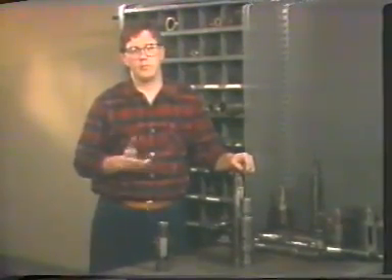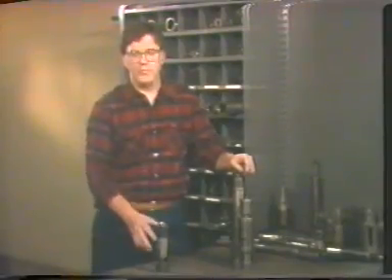Pulling tools are designed primarily to be used to retrieve subsurface devices from the tubing bore. Such devices are designed and constructed to provide a place near the upper end of the device for a pulling tool to engage or latch the device so it can be unlocked and retrieved from the tubing bore. This part of the device is commonly referred to as a fishing neck.